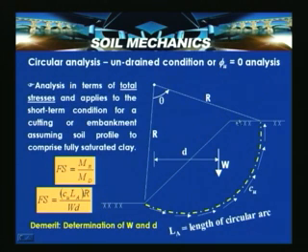So, here a cross section of a slope is shown and this is the failure surface, the possible critical failure surface. r is the radius, and W is the weight of the wedge, which is determined by the area, per meter width of the section perpendicular to the plane of this figure, multiplied by the unit weight of the soil. If this location is shown as the CG of the entire section, it is located at a distance d from the center of rotation.